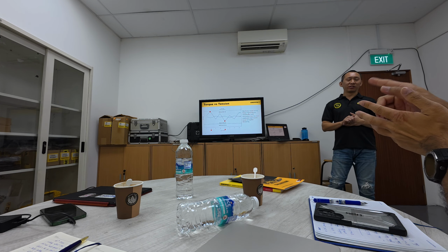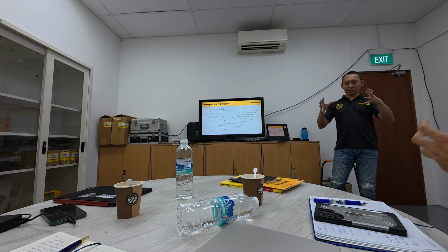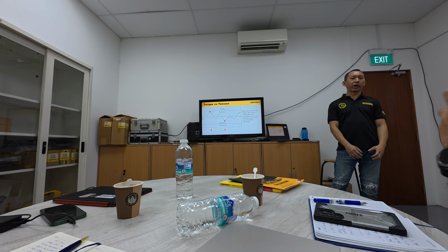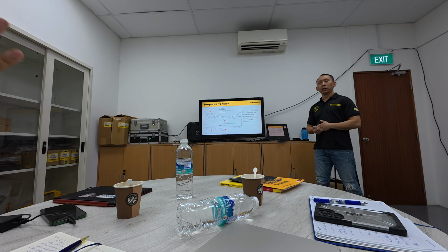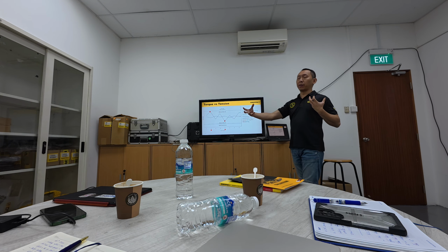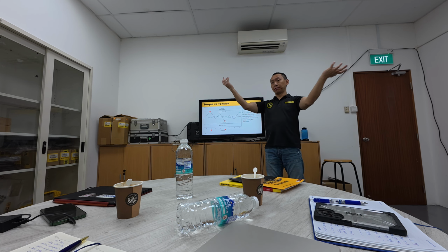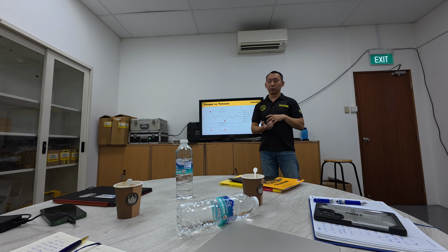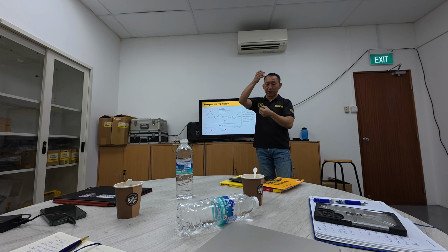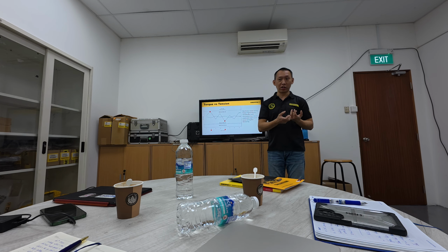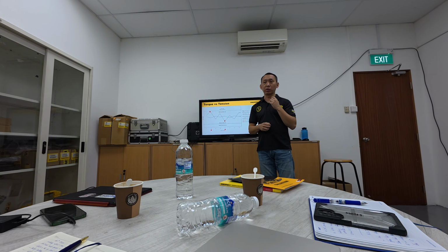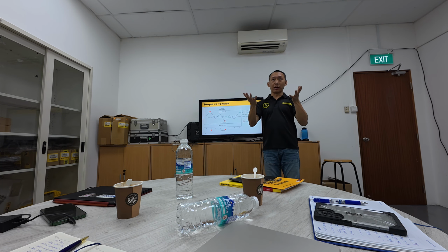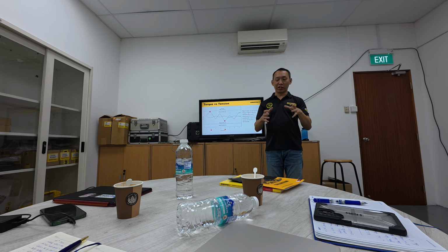The key point to select whether to use a torque wrench or bolt tensioners is what kind of joint, and whether there is enough space. If we are not talking just about pipeline but also equipment, for example a crane, whether using a torque wrench or a tensioner is better also depends on what type of space is allowed, and whether the stud is long enough or not to do the tensioning. So it really depends on the conditions and factors on the joint.